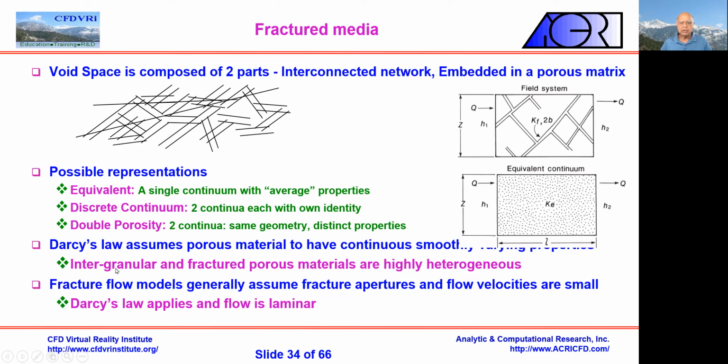Okay, so Darcy's law basically assumes that there's continuous smoothness, but we have generalized it today to deal with anisotropic or inhomogeneous materials. Okay, and Darcy's law basically fails if flow becomes very fast, much more than a Reynolds number of 10, which is kind of considered the limit, and this happens in fractures.